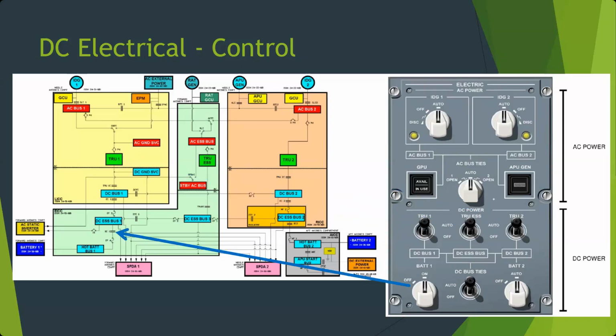The hot battery bus can also often serve as an emergency bus. That's why when we power up the 727, we plug in the battery and go up in the cockpit and there are a few lights on, a few indications. One of those is the stall warning system. It can run off DC battery. If the battery's plugged in, the stall warning system is working. Because it's that critical to the airplane, whether it's flying or gliding, you want to know if it's stalling or not. You want to make sure it's not stalling. So that's hooked to the hot battery bus, for instance.